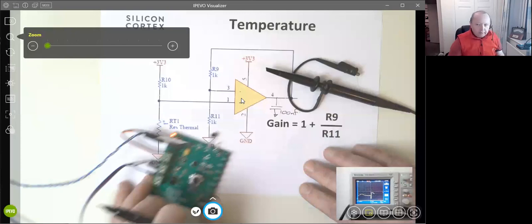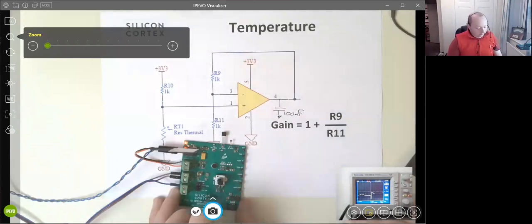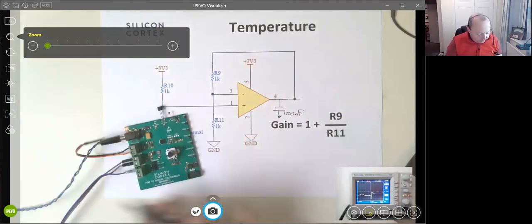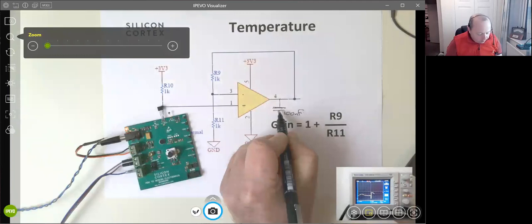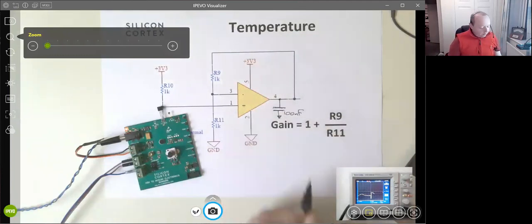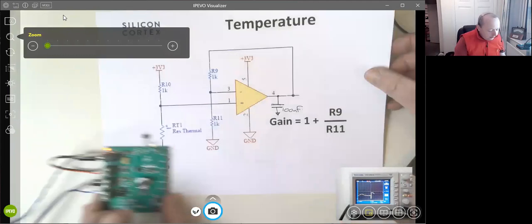It's because I was experiencing some noise problems in the signal on the oscilloscope. When we talk about product reliability next month, we'll talk a lot more about the use of capacitors to solve noise problems on boards. But if you do have a noise problem on an analog circuit, chances are a capacitor in the right place, costing 0.1 of a penny, will fix your problem. So there's a top tip.